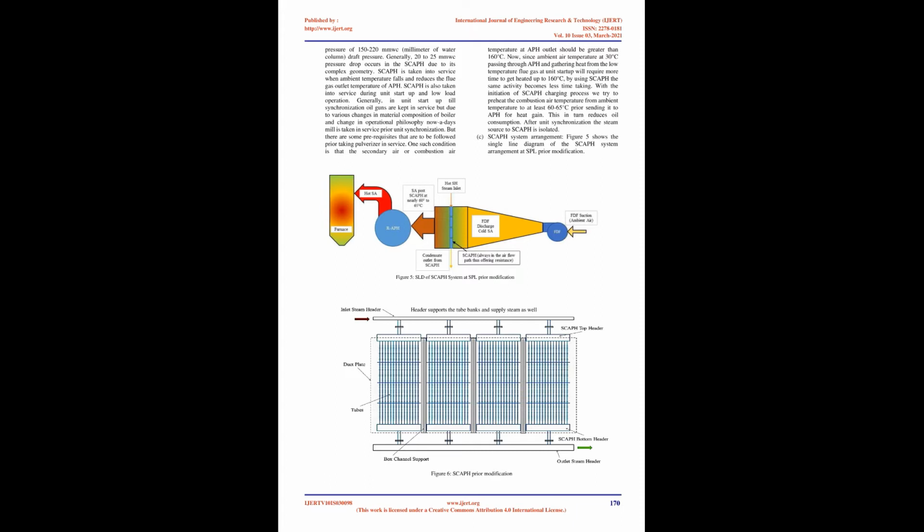Boiler. The boiler at SPL is a supercritical, variable pressure operation, spiral tube once-through, single furnace, single reheat, tangential firing, balanced draft, semi-outdoor arrangement, 2-pass type manufactured by Shanghai Boiler Works Co. Ltd. Turbine.